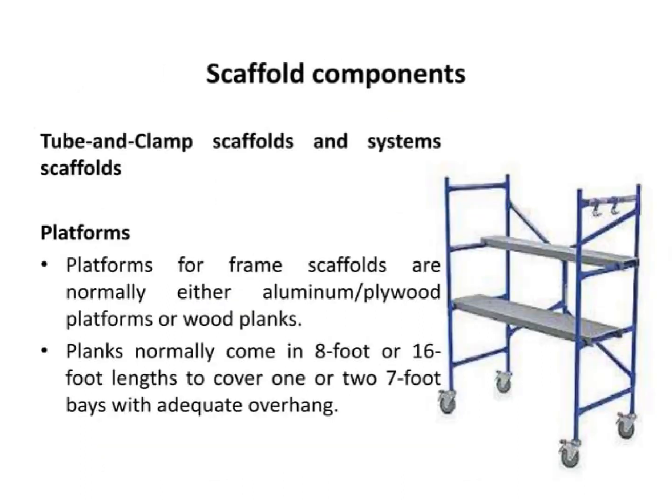Scaffolds made of tubes and clamps are highly versatile and can be used for a wide range of projects. The frames are constructed with tubes and connectors, which are then covered with aluminum or plywood platforms of 8 or 16 feet length. When installing these planks, it is important to provide sufficient overhang for safe working conditions.